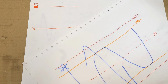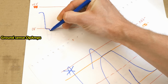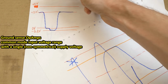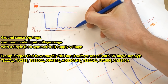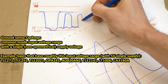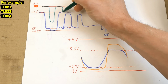And of course also in some op-amps the range of input voltages is limited non-symmetrically. This is quite common for op-amps optimized for a non-symmetrical supply voltage. The input voltage can go to the negative rail or even a little bit beyond, but it can't go too close to the positive rail. For example, for some at 5 volts, the limits are from minus 0.2 volts to plus 3 volts. So they can be used for small signals around 0, or for signals going between 0 and a certain voltage in the positive side. And there are even types limited non-symmetrically the other way, where the input voltage can go to the positive rail, but not to the negative one.